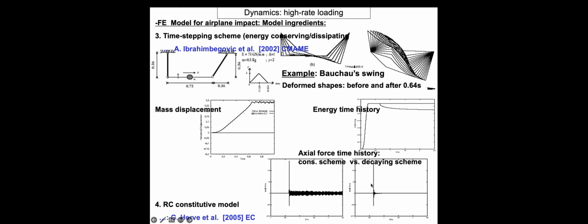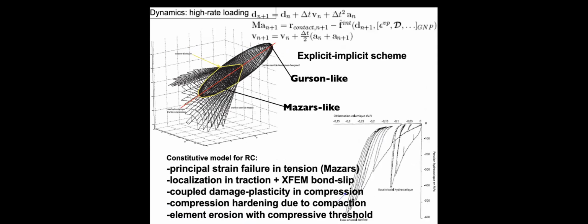But if you now use the energy decaying scheme, you simply take out these things and then you can carry on smoothly. You can see that the energy that you take away is not that big. High vibration modes are not that important. You still have this energy decaying and it improves the result on your stresses. So this also was tested to get the proper interpretation. And then we want to run this with the central difference scheme because this is a very short duration type of impact.